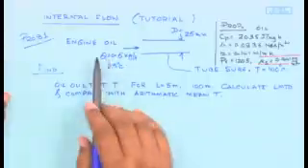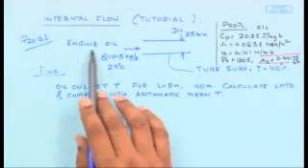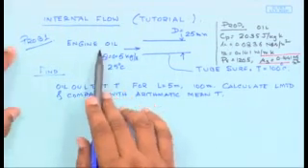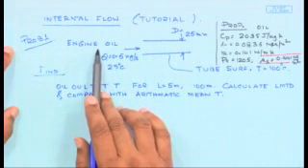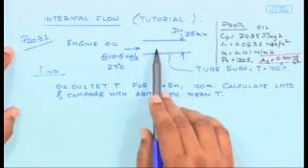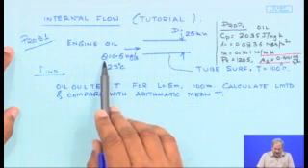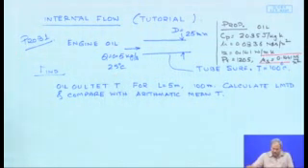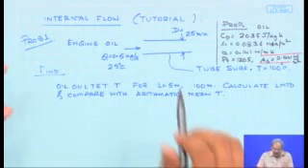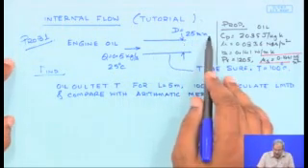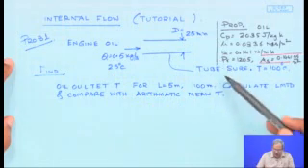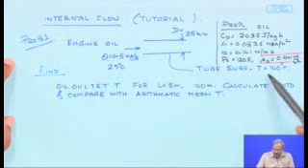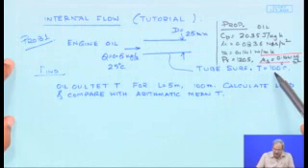So today we are going to concentrate on a few problems. The first problem deals with a fluid, engine oil, which is characterized by a high value of Prandtl number. Engine oil is entering at a rate of 0.5 kg per second and at a temperature of 25 degrees centigrade into a tube whose diameter is 25 millimeter, and the tube surface temperature is maintained constant at 100 degrees centigrade.